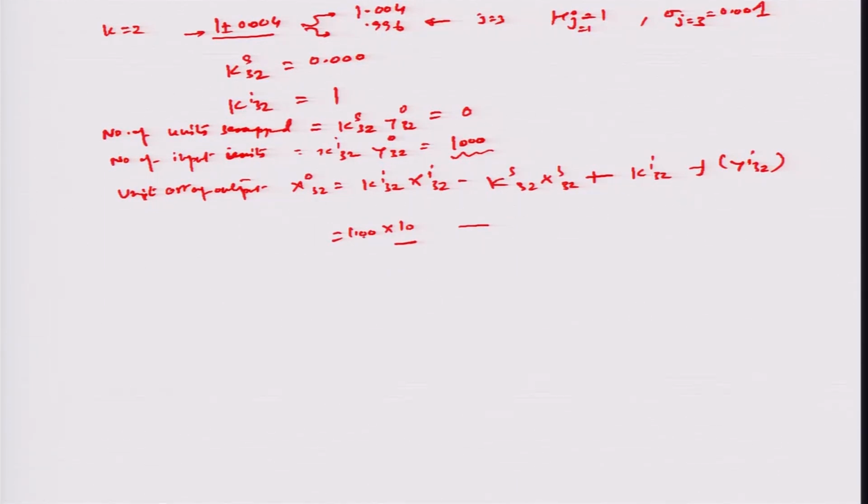So, it is 1.00 times of 10, that is the unit input cost, times of the scrap coefficient, 0 times of almost 0, there is no scrap, sorry, the scrap cost is $2, but there is no scrap. Okay. So, this component is 0, times of 1 times the processing cost, which is again $12 per piece. So, this happens to be about $20, $22 per piece.